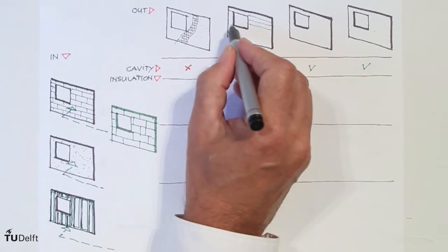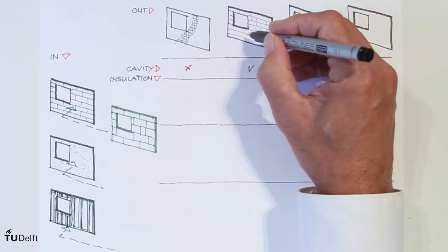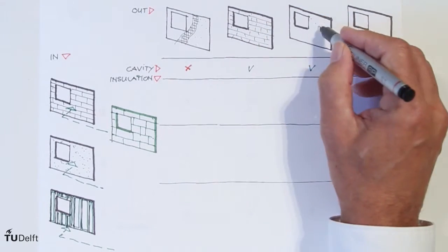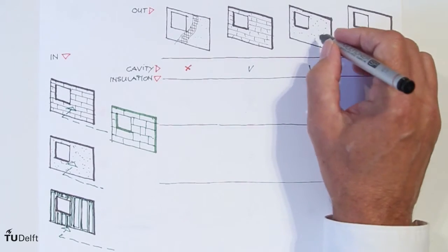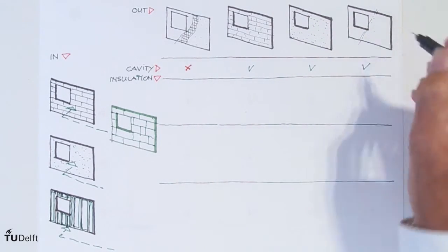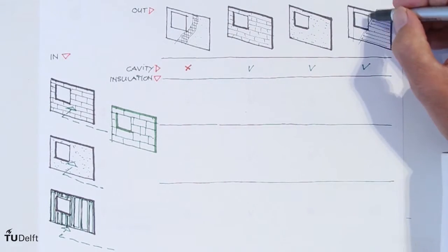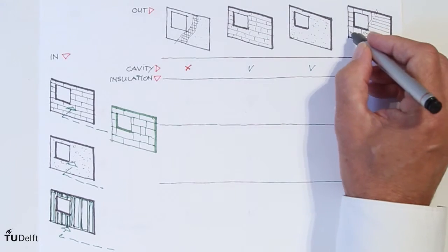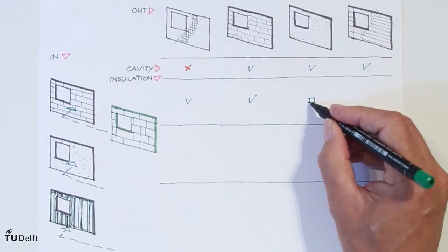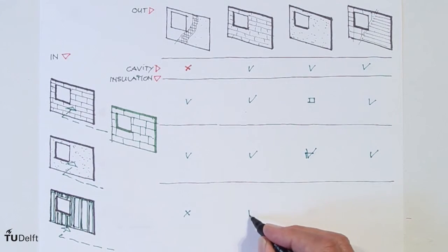In the other 3, a cavity separates the outer layer from the thermal insulator. The outer layer itself can consist of blocks, large plates or a system of boards, planks, small plates or shingles fixed on a system of rails. All combinations of inner and outer layer are possible, but in case a heavy concrete outer layer is used, it can't be anchored to a block wall or stud wall and must be anchored to the main load-bearing structure.